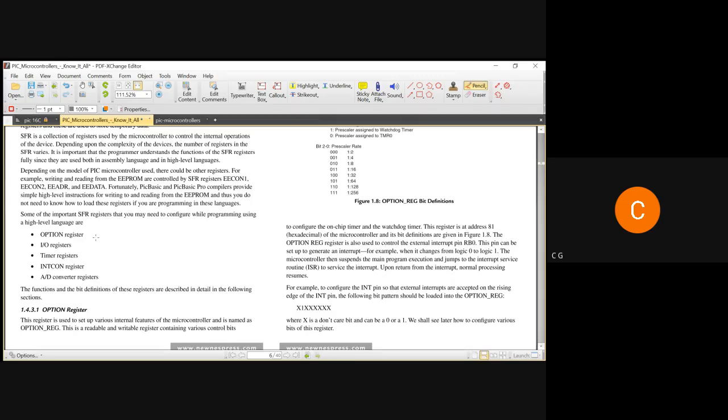By accessing these zeros and ones, either by the user or by the microcontroller, the controller will know what I am doing right now. Or when I am transferring data, I need to set some register value to one to enable the communication, and then I have to disable certain things, like if I am sending data out, I have to disable the incoming data. That operation has to be done.